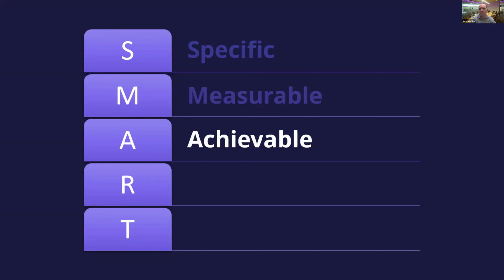Achievable. Listing unnecessary requirements drives up costs and adds complication. Be careful of the nice-to-haves, such as redundancy on machines or increased throughput based on an idea it may be used in a few years' time. For processes with a large number of finished parts, look and see which products or SKUs are low volume and might not need automation. Running a large number of SKUs also drives up cost and complications in the machine, which often reduces reliability.